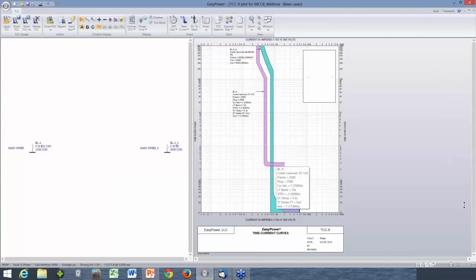Down here is the short time delay adjustment. This is the short time trip, and then we have the instantaneous. So you have much more adjustability, and up in the long time range you get a bit more accuracy in the settings. With the smaller thermal-magnetic breakers, this thermal band can get quite large. There's a lot of variability in the breakers themselves.